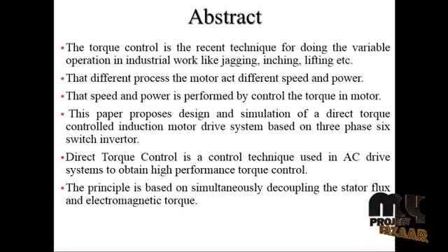This has been achieved thanks to a suitable combination of the 4 unbalanced voltage vectors instantly generated by the 4-switch 3-phase inverter, leading to the synthesis of the 6 balanced voltage vectors of the 6-switch 3-phase inverter. This approach has been adopted in the design of the vector selection table of the proposed DTC strategy, which considers a subdivision of the Clarke plane into 6 vectors.